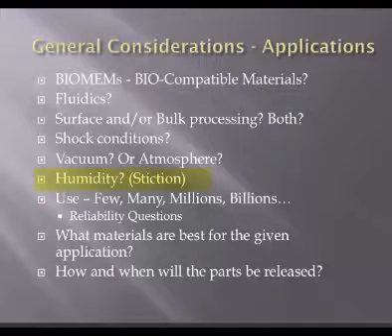So if you put humidity in contact with polycrystalline silicon, right, the water can collect on it, and it can actually cause it to stick. Because when you're talking about very, very small separations, small distances, if you get any fluid in between those surfaces, they can stick together. Just think about taking two glass slides, maybe I'll bring them in one day, breathing on one, sticking the two glass slides together, you'll never get them apart. That's stiction, right? So how do you mitigate that?